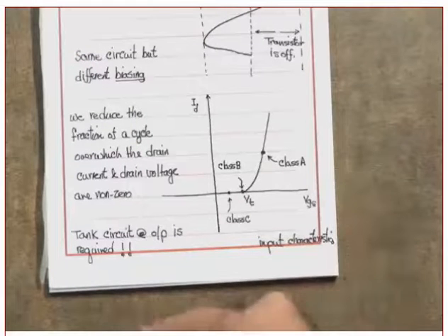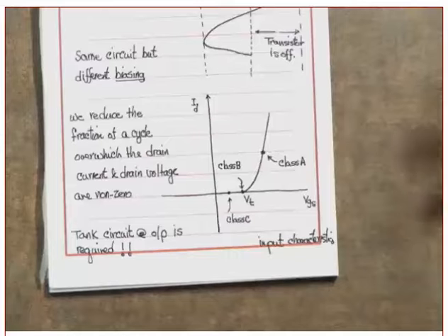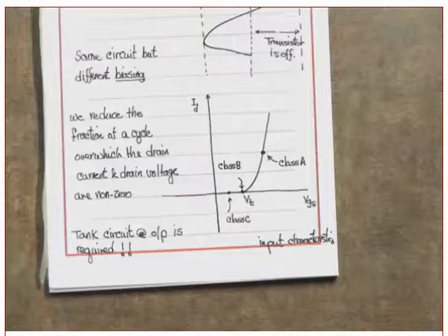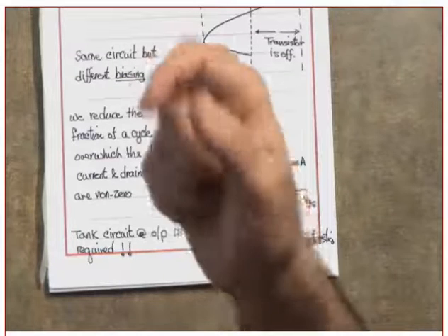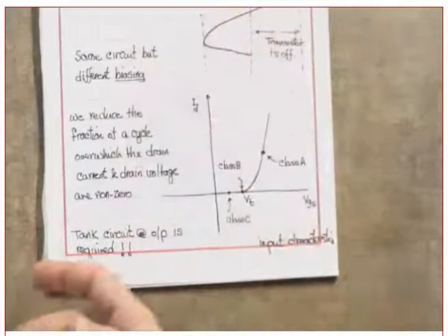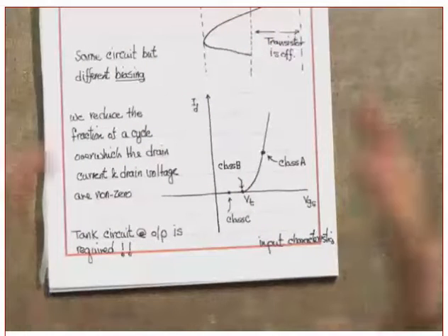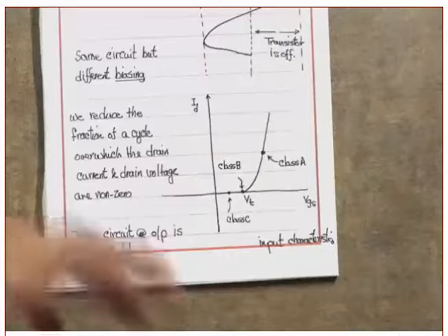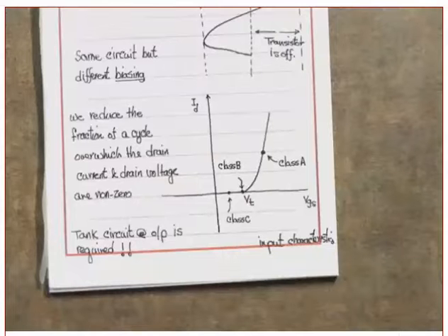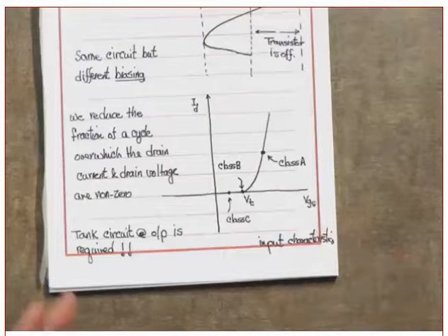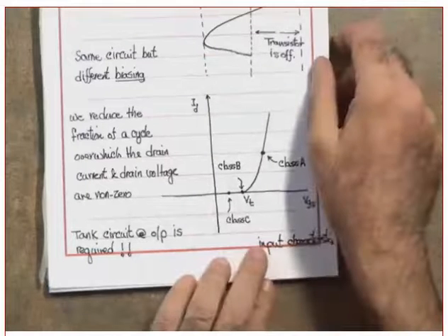The voltage at the gate needs to be higher than the threshold voltage. Why? So that the N channel, for example, or the P channel, depending on the type of mode that you are using, needs to be created, induced. Clear? For the electrons to pass from the source to the drain, which means the current is in the other direction.